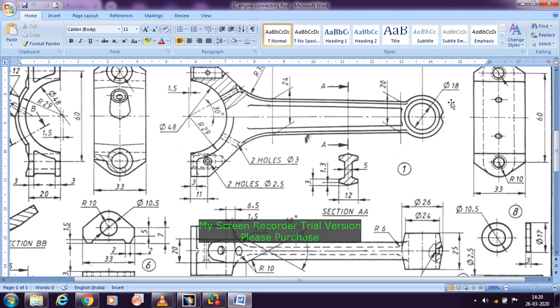Now in order to take these dimensions, we need to see the section plane. When you cut this portion along the horizontal axis, you can find the section like this for the cut portion. With respect to this axis, you need to create the profile like this. Draw the straight line, then a horizontal line, then a slant line, and then close the profile. That I'll be doing here.